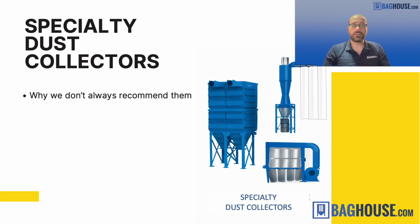In the picture here, you can see some envelope collectors, which is an older design that's not used so much anymore. It's mostly been replaced by baghouse styles with round bag tubes, filters. But the other two you see, the one is a cyclone that then has filters hanging off of an outlet header. And the other is a baghouse that has inflatable bags, one that goes up and one that goes under. So these for many years were very common in woodworking. These are what are called enclosureless baghouses.